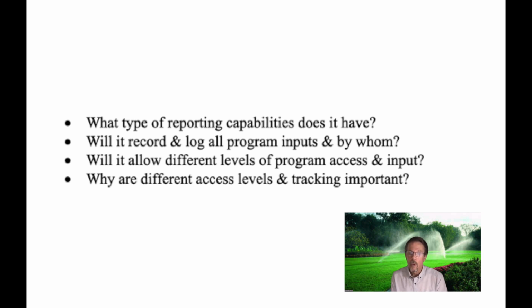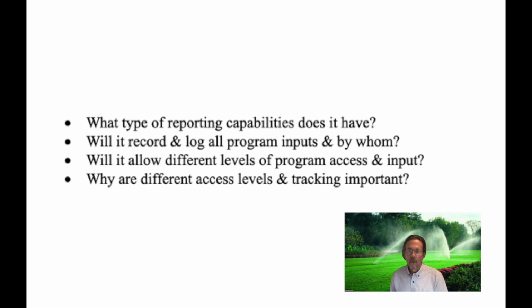Will it record and log program inputs, and by whom? This will enable accountability and help to define the responsibilities of all parties. Will it allow different levels of program access and input? Why are different access levels and tracking important? An example might be you'd like the service contractor to have the ability to turn things on and off when he's providing service, but you might not want him to be able to change programs.